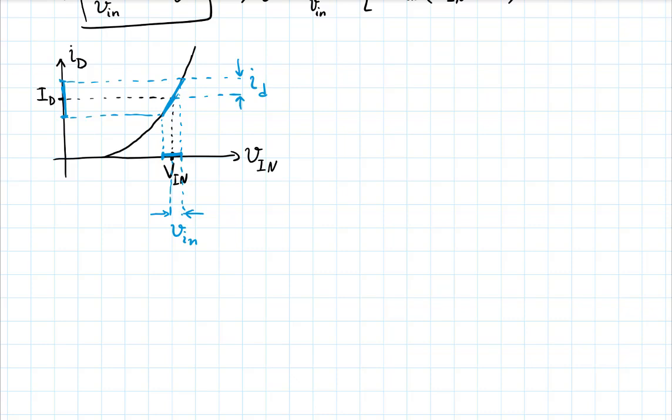And you can see that, of course, the slope depends on around which point on the curve I'm operating. If my V in was smaller here, I'd have a smaller slope. If my V in was larger, I'd have a larger slope. The question here is this. What if my bias point is at V in equal VT, right, where I have not quite turned on the device yet, right at this point VT? At that point, if you add a small signal to it, you will have this small slope there, right? Now, what is the slope at that very point?